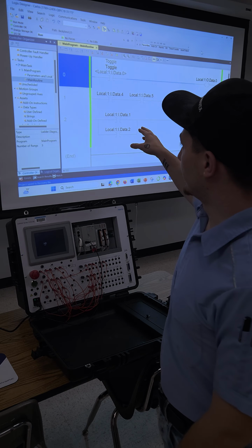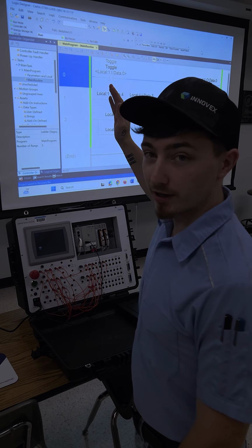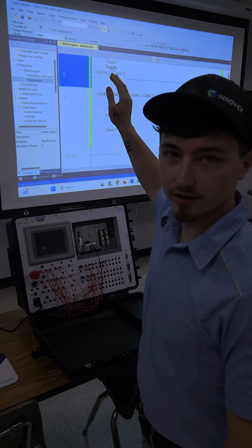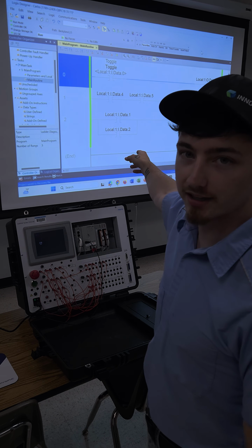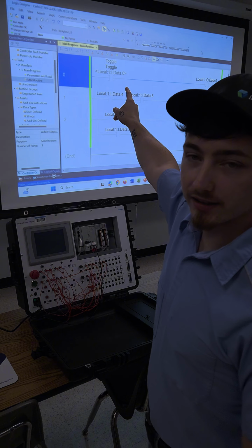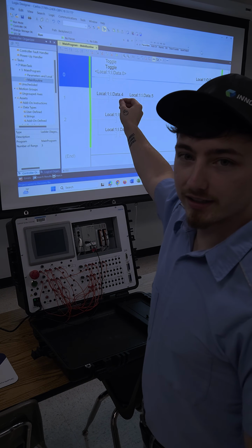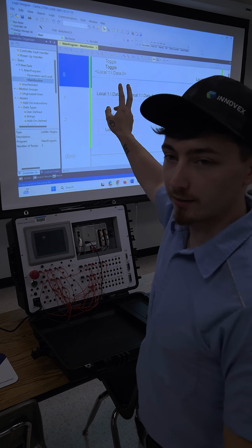And so this is ladder logic with the power rails on the sides and the rungs in the middle. So you can see we have 3 rungs and then an end rung at the bottom. If you look at 0, this right here is an XIC, or examine if closed, contact right there.